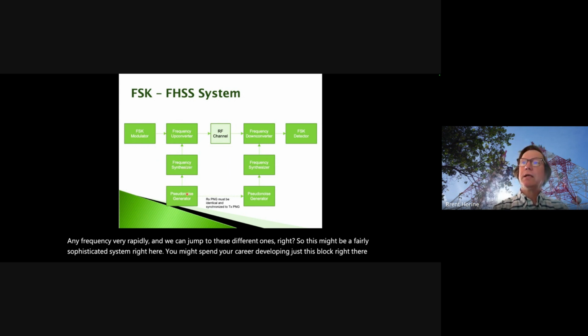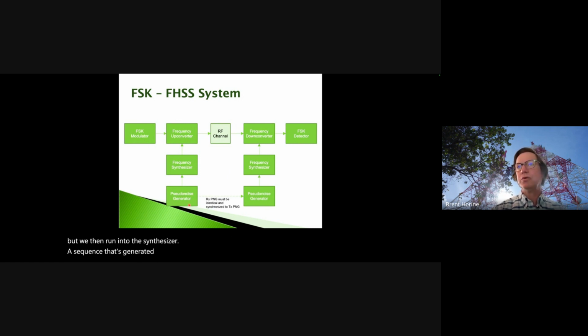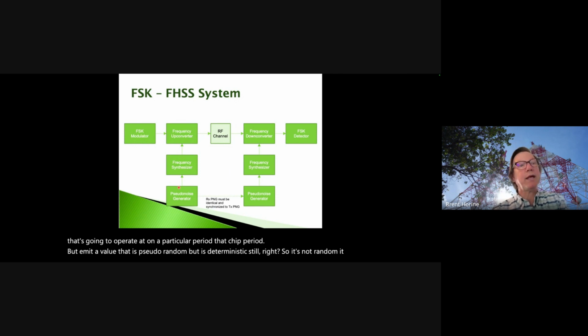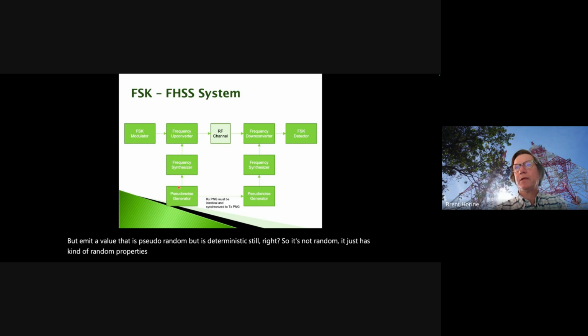But we then feed the synthesizer a sequence that's generated by this pseudo noise generator or pseudo random generator. And again, that's going to operate on a particular period, that chip period, but emit a value that is pseudo-random, but is deterministic still, right? So it's not random; it just has kind of random properties when we look at it, right?